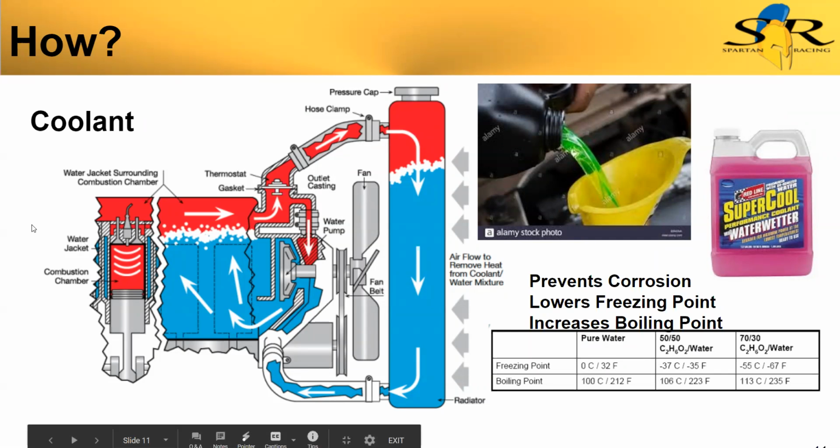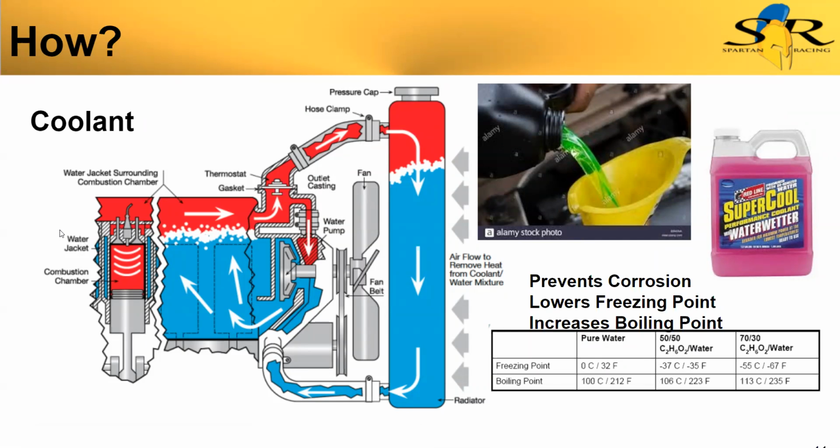Coolant in colder climates keeps the water from freezing in your engine. If it freezes, it's going to expand and close off passages, and it will pop out your freeze plugs, which are designed for that purpose, so it doesn't actually break your engine.